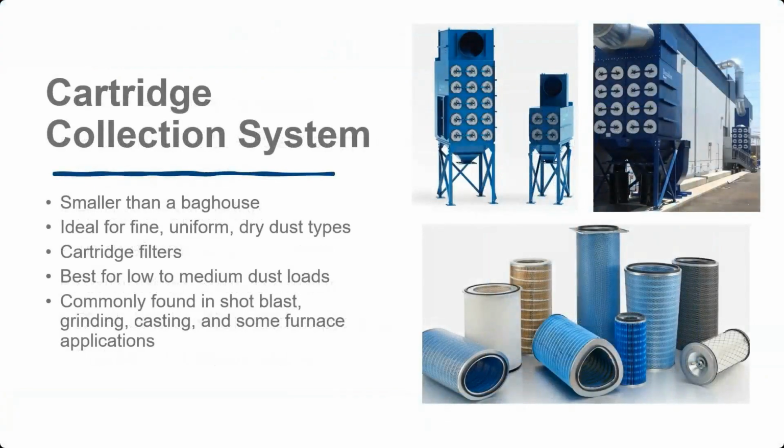There's a lot of different styles of dust collectors out there, but the two styles that I'm going to focus on today probably make up 95% or more of the collectors that you have on your site. The first style is the cartridge system dust collector, and the cartridge collectors are really great, and they're primarily used in the shot blast and finishing areas.